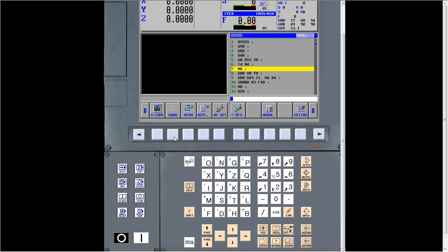But within your fixed forms, you could set something up to where with specific materials you could set up spindle speeds and feed rates and everything with a fixed form. But it does not have a material table where once you do a cycle or a program where it goes up and picks out cut speeds and feed rates based on different types of material or tooling data or anything like that. There's nothing like that within Manual Guide I.